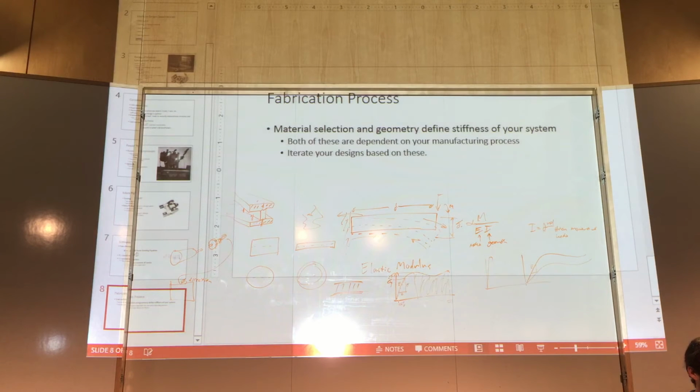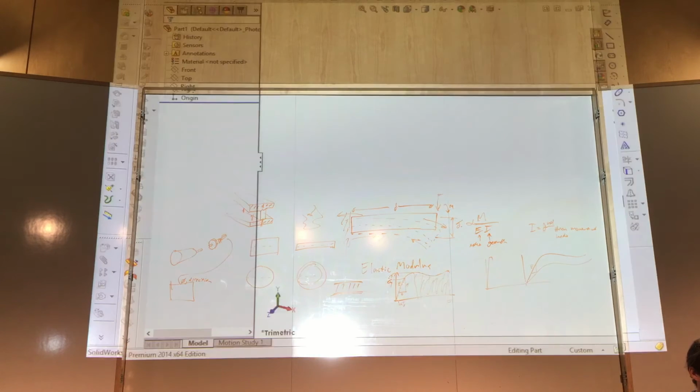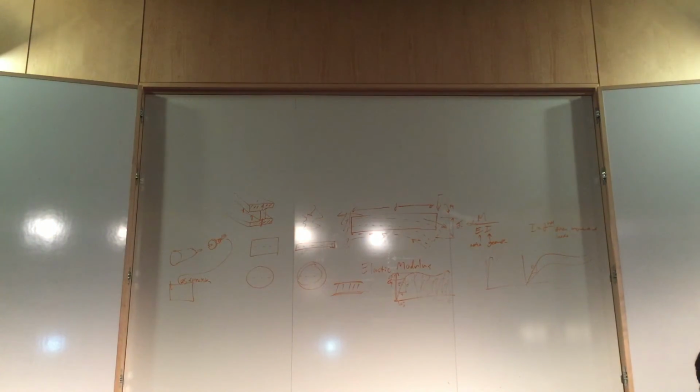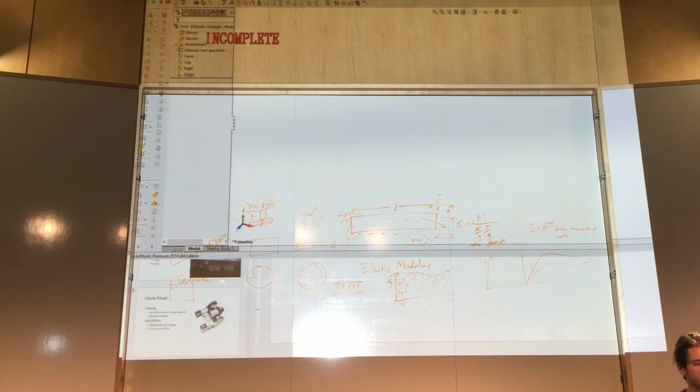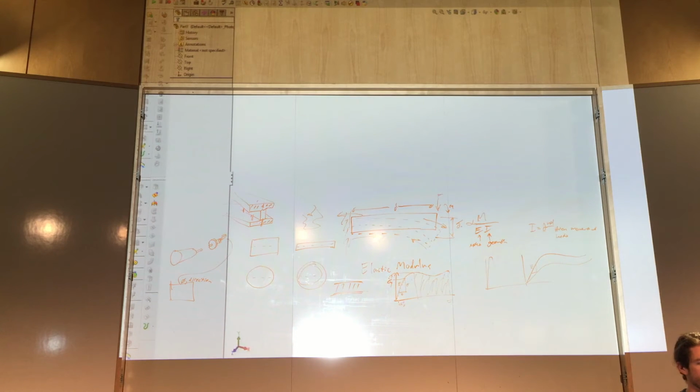So you talked about the slider mechanism with the 2 parallel linear slides and 4 bearings on them. That's actually over-constrained, right? It is. So what are the strategies for that? You usually will build some sort of compliance into the extra constraints.